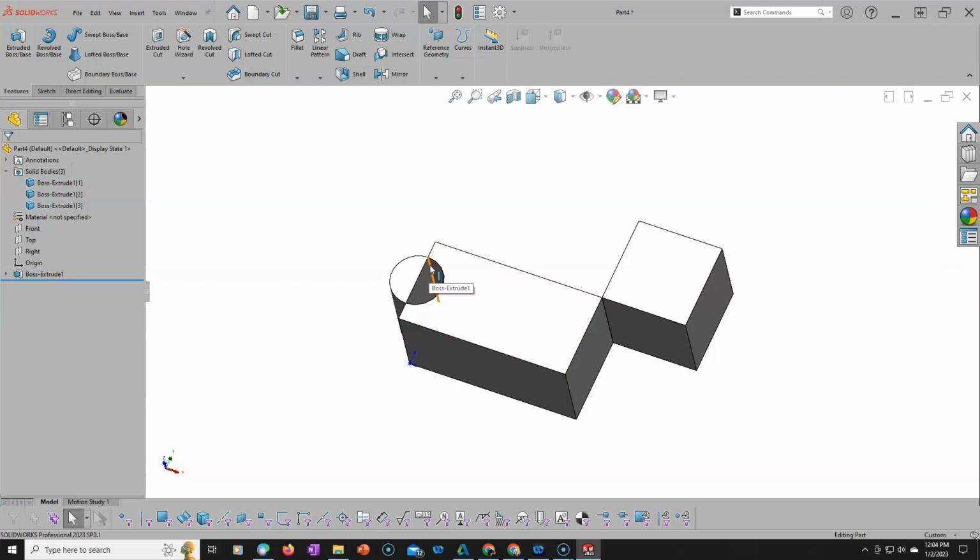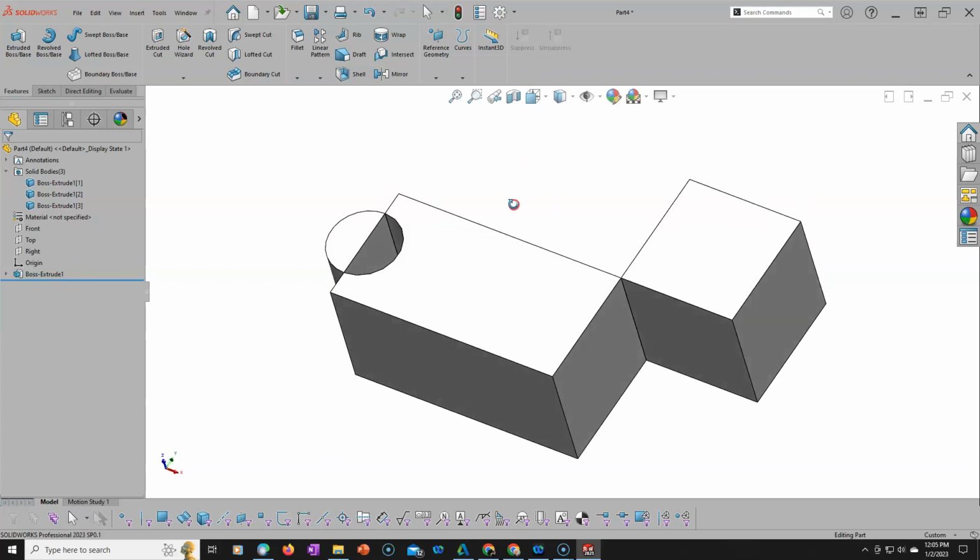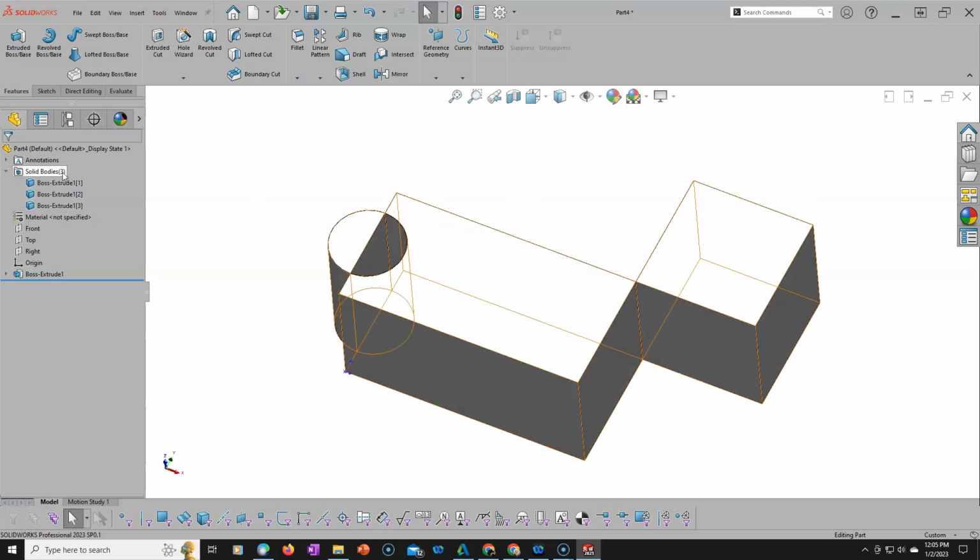And at each of these intersections, inside here and inside here, I have 0 thickness geometry. So there's no way for it to merge because that edge and that edge are just touching. There's no overlap, no intersection, or if there was a gap, I would still get the solid body. Depending on the geometry is what you're going to end up with. And if I see those solid bodies, it's kind of an error check of, did I intend to do that and I wanted to see those, or did I not intend to do that, and why did I get those?